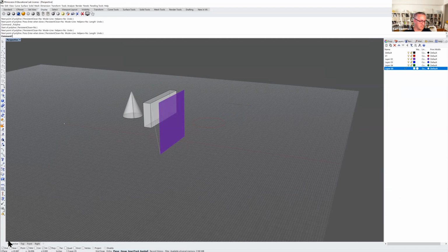And so for me, if I watch you modeling something and you have near on, near seems like a good idea, but it's a really bad idea. It just means that it'll basically snap to anything that's near it. And so I would never, ever have near on unless I'm not trying to be so specific or too accurate about it. So what you can do is turn some of these on and turn some of these off